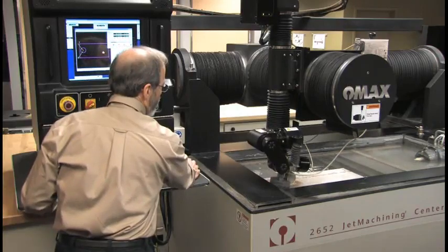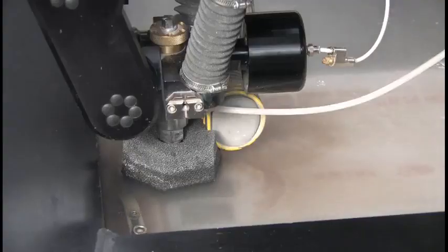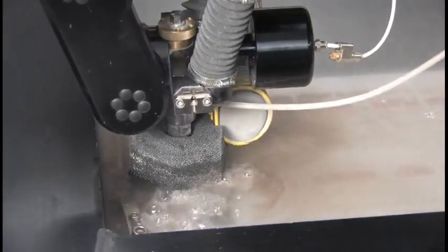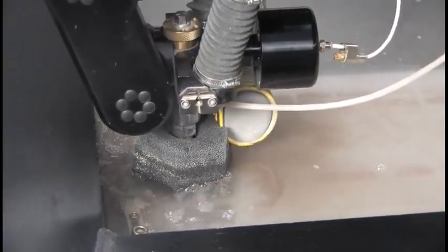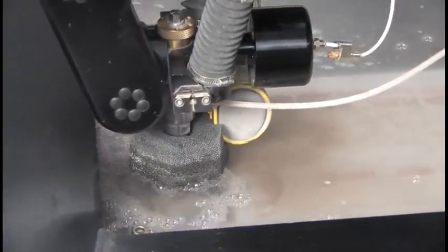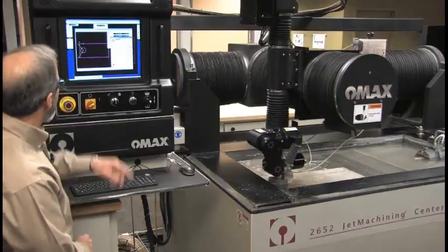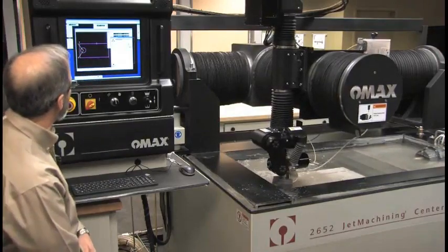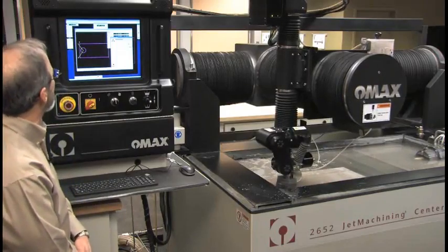It's going to quickly auto square my tilting nozzle here. This gives me the most accurate part using this tilt-a-jet. And now I'm ready to start. Going ahead, making first the circle in the center, and now it'll make the outside of the part. And now you can see how that controller is coming in. It's allowing it to go fairly quickly along the straightaways. Then it'll slow down automatically for the corners, again to give me the part quality I want.